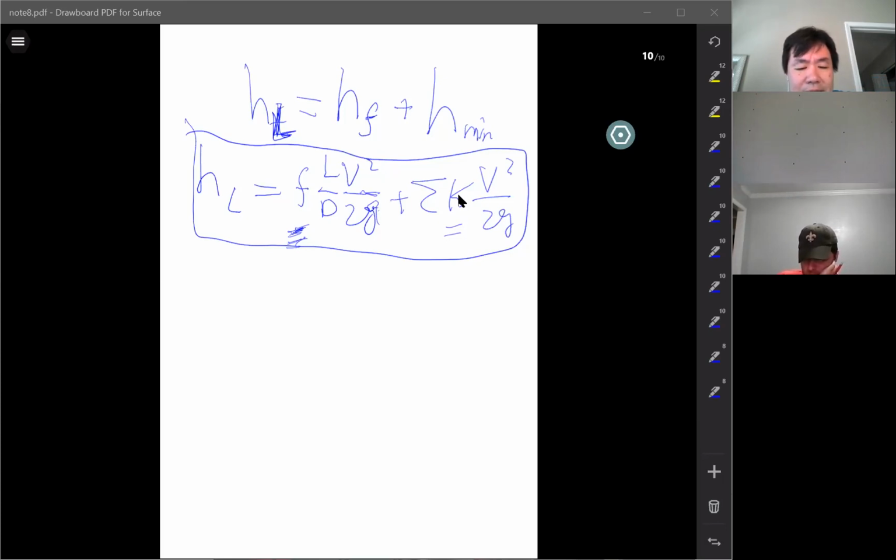It gives you the K for each different situation. For example, pipe entrance: even the entrance will give a little bit of loss. Contraction: if you have a contraction, there will be some loss due to that contraction. Expansion, same. Bend: you'll have some loss in the bend. The 90-degree mitered bend and the 90-degree smooth bend have different cases. For the smooth bend, you see the K is related to the radius of the bend. Also there are other pipe fittings, including all kinds of valves, when wide open and half open, the T, the elbows. Everything will contribute a little loss to the piping system.